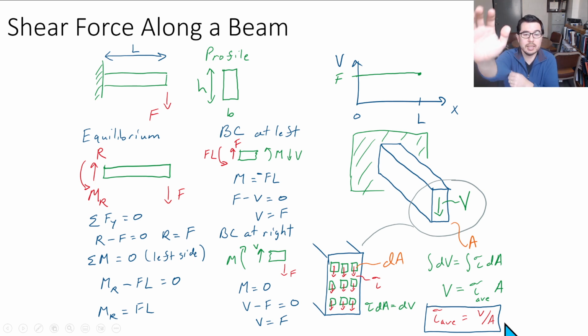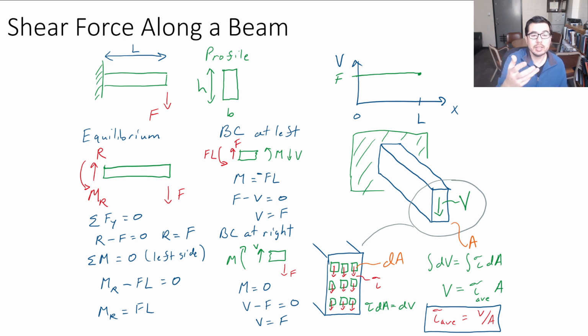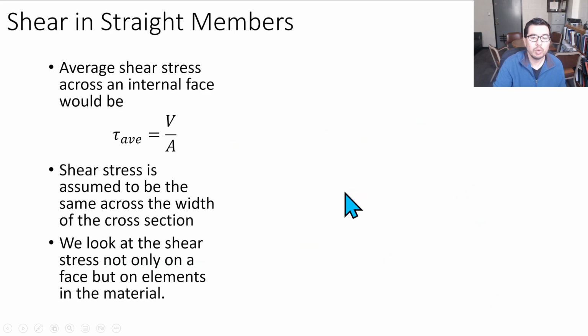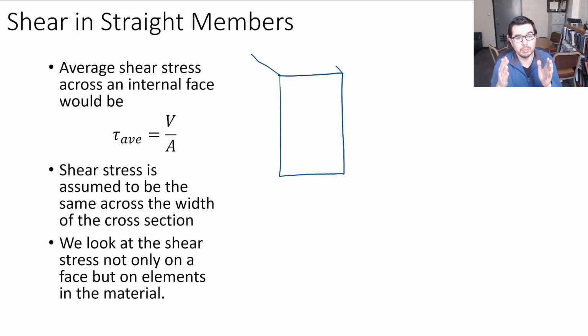And you're thinking, we just did this. What does this look like? This looks like the single shear case, where we just discussed that if I shorten the length quite a bit, I get a situation where I have very little bending moment, and it's dominated by the shear force. So one thing that we do keep track of is this average shear stress, an important quantity when we're looking at shear in a beam.